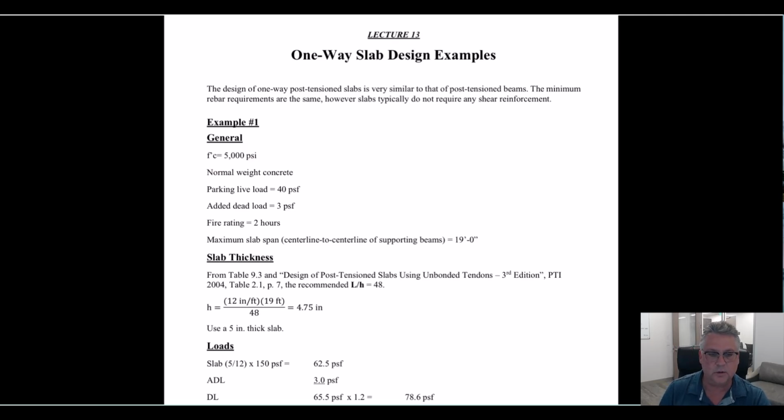Now, I did give you a project, and I changed that stuff up and made some storage and changed the occupancy each year, but that's just for fun and using different loading. But the reality is, if you're doing one-way slabs and beams, you are probably working on a parking structure. As a parking structure, you typically have a 2-hour fire rating. I'll talk in a minute about why that matters.